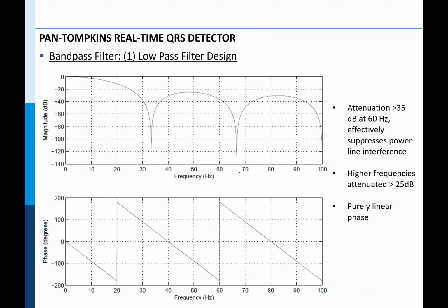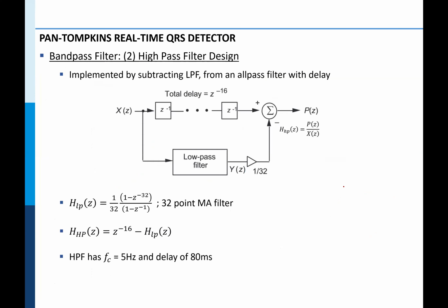And this is the frequency response of the low-pass filter, which has both the magnitude response and the phase response. If you see the magnitude response of the filter, it shows the low-pass behavior of the filter design. And the other advantage is also that within that frequency range of interest, the phase response behaves in a linear way. So it's a linear phase low-pass IIR filter here.